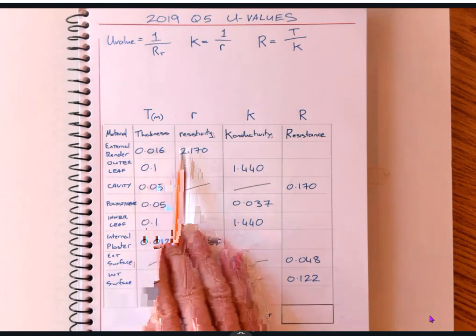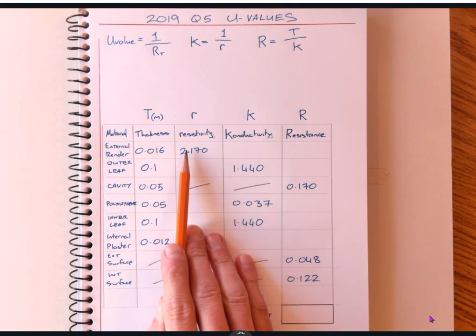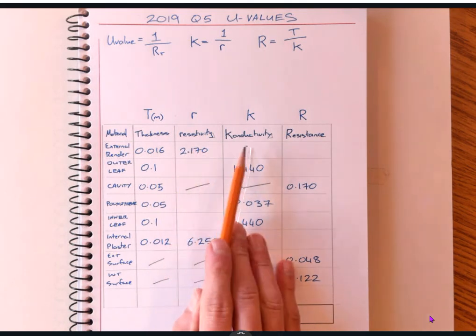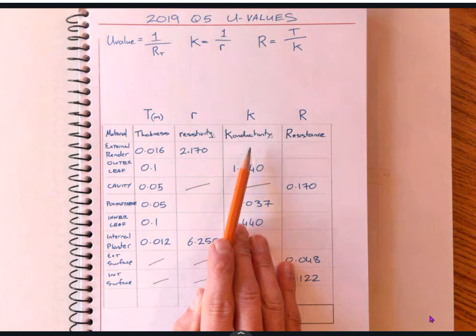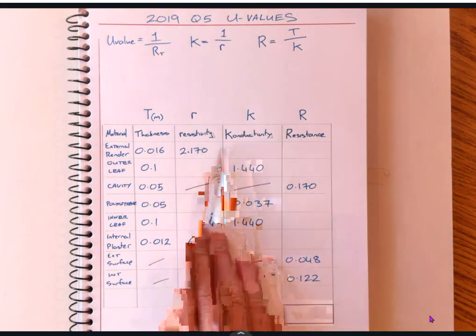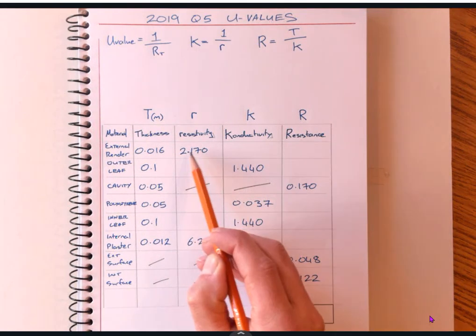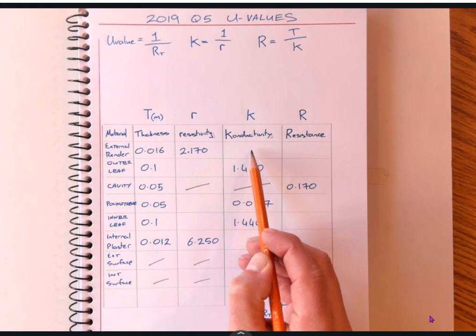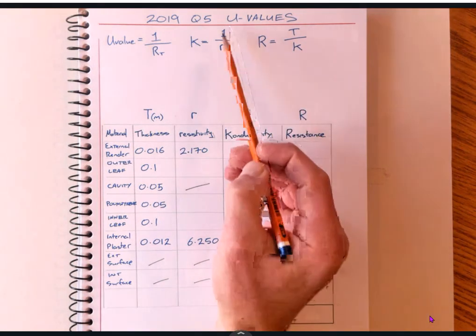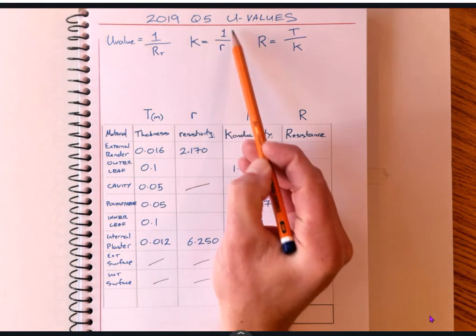We'll start at the top. Basically, if I've got a resistivity measurement, I need to turn the resistivity into conductivity, and then figure out from that the resistance. So this is the most work I'll have to do. I've got resistivity, I need conductivity. If I look up here, our second formula: conductivity equals 1 divided by resistivity.